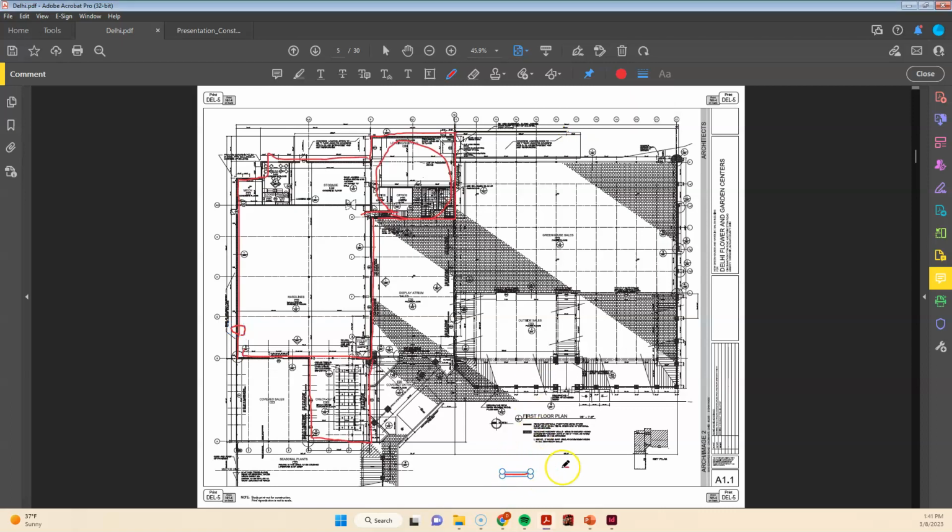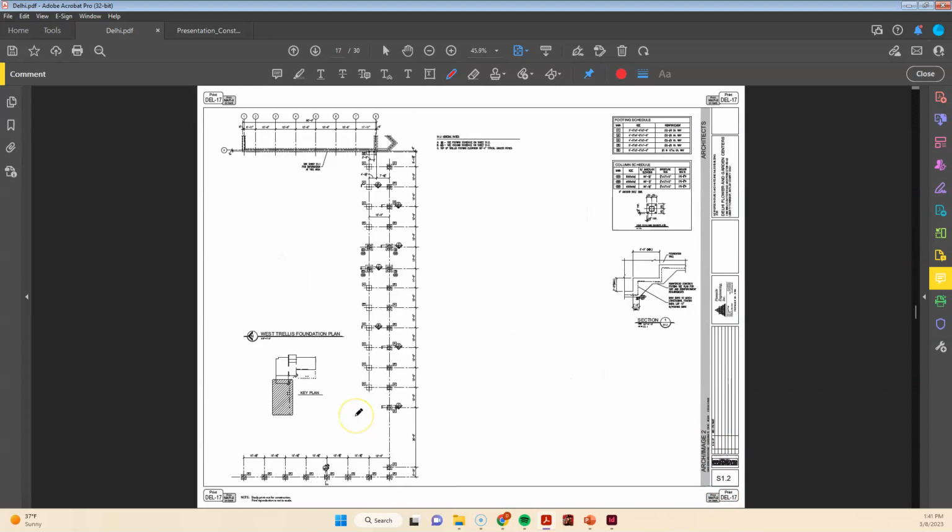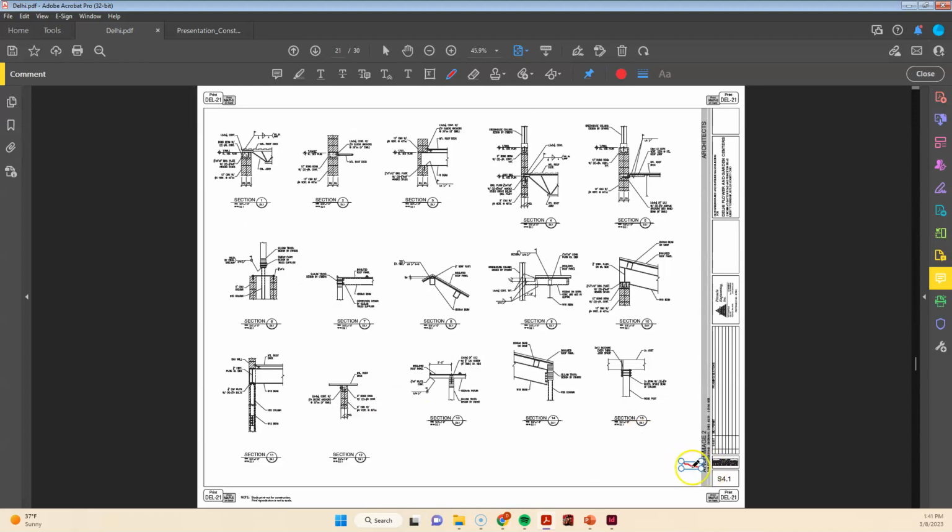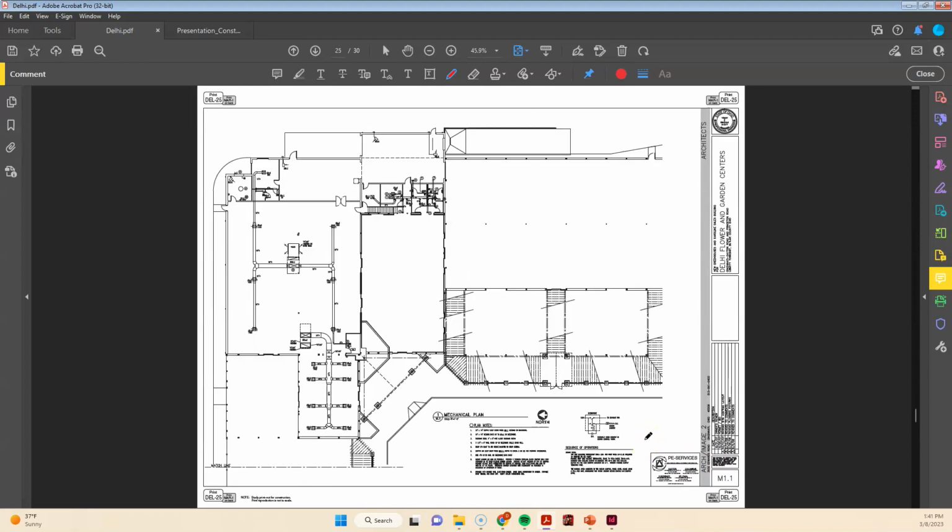I'm going to jump ahead real quick to one interesting drawing, even though I said I wasn't going to look at the mechanicals. So A11 is the floor plan, and I'm going to scroll all the way up past structure, so I'm looking down here. Plumbing, mechanical. So here's mechanical 1-1. And why I would come here is because with these greenhouses, I'm curious what's heated and cooled and what's not. And so this is the same floor plan, laid out just the same. There's the north arrow. And this is showing me this is all ductwork, providing heat and cool.